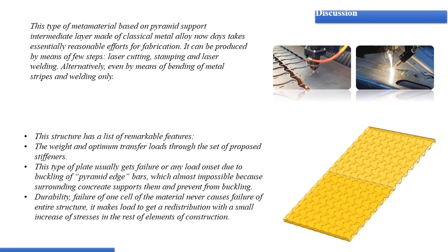And another thing is that usually the failure we can get in this type of structure is buckling of one edge of the pyramid. But if it's filled with concrete, it is almost impossible, because the surrounding concrete supports them and prevents buckling. So that's probably the secret why it's so strong in comparison with the conventional plate.